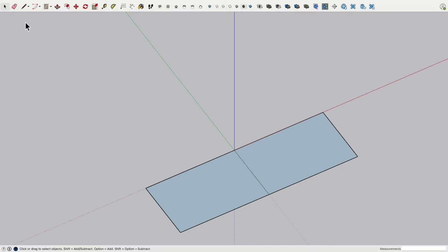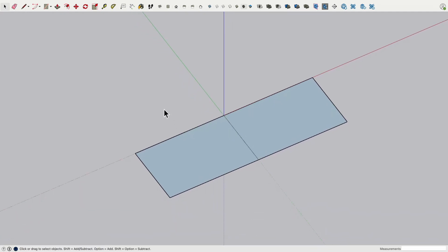Now, let's take a look at the rectangle we drew so you understand what's happening. We're talking a little bit about the geometry of how SketchUp creates sketches and 3D models. This is a fill, and then this is an outer edge. You see this outer edge is actually bold. And then here is an inner edge that's thinner. The outer edge we can also consider a contour. And you see here we have two fills divided by this inner edge. And then here, this outer edge, we have two on each side simply because of this line.